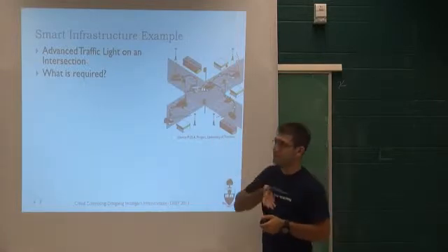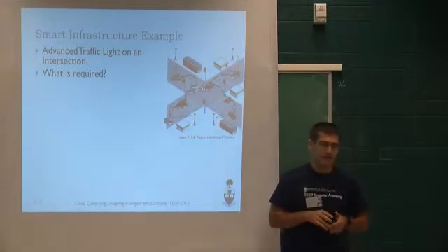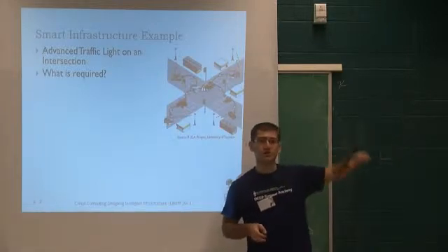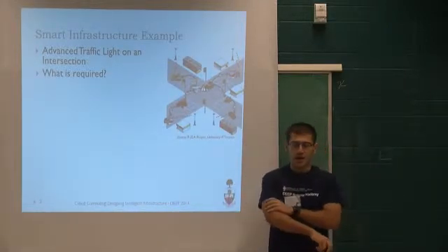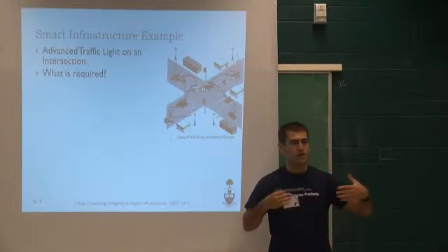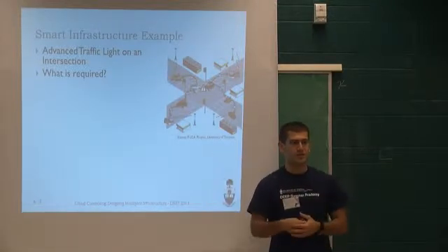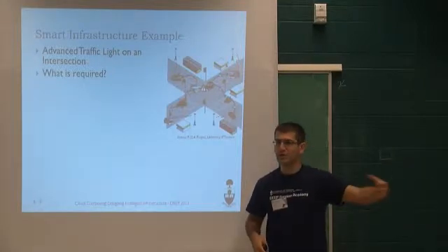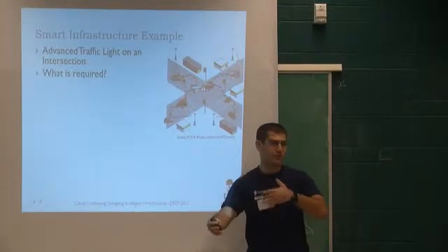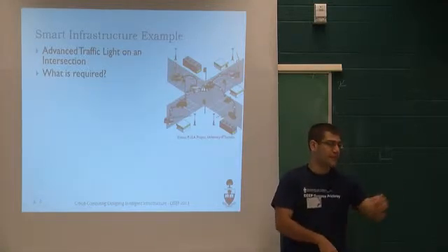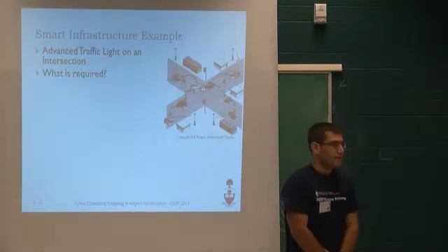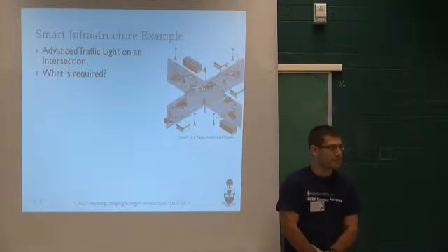If you have a major road such as, let's say, St. George, and then you have a smaller street like Harvard, a bit north of here, how do you decide which direction has a longer cycle? So how long the vehicles would be going in one direction, then you stop it, that gets a red light, and the other direction goes. Like where I live, at Station Minor Road, they have a sensor in the road. If it detects that there's no car there and no one has pushed the pedestrian button, it will extend the time on the major road.